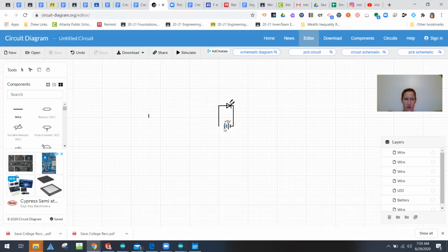And now I want to talk to you about conventions. Whenever we make a circuit diagram, we are going to color code our wires. The reason we're going to do that is because it's a good way of thinking about how the circuit works and understanding the circuit. And it will help us with our actual wiring as well. Every time you have a wire that's going to ground, it's going to remain black. And every time you have a wire that is coming from 5V, then you need to code it as red.